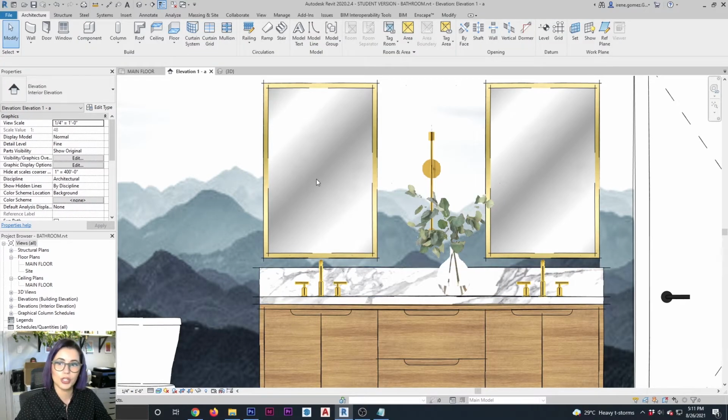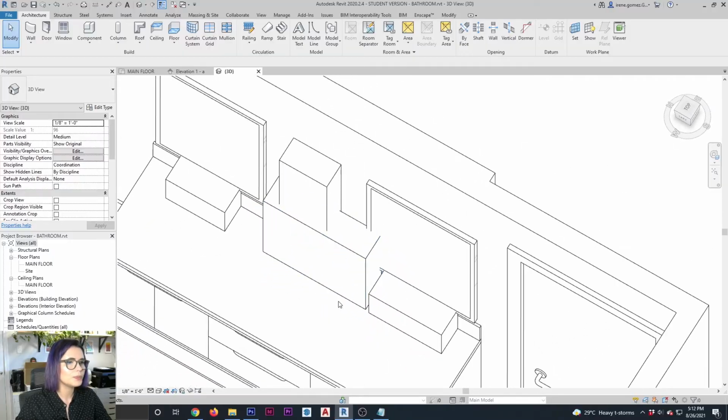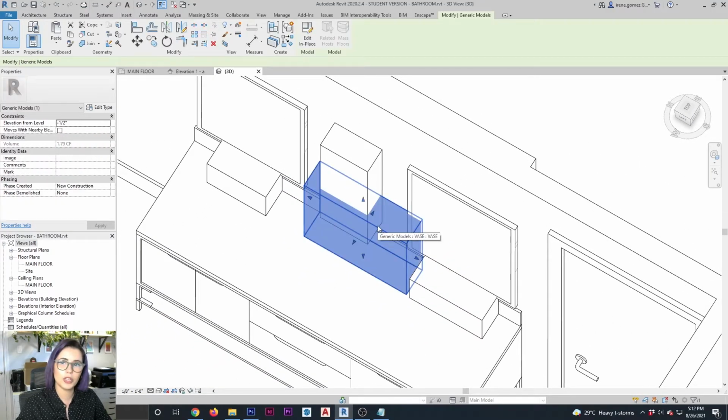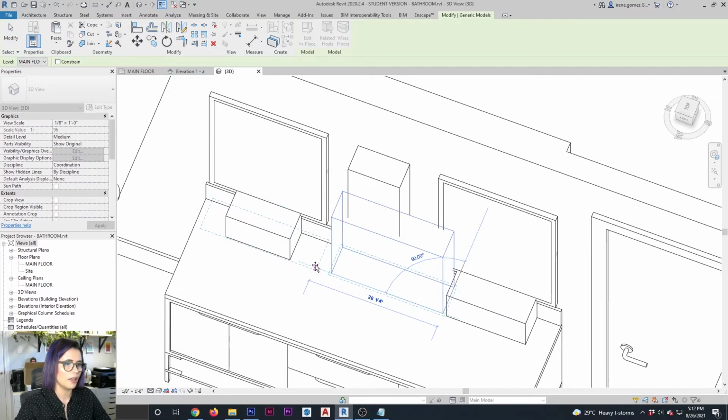And we're gonna finish this exercise with creating those cute Aesop bottles that are like for fancy people. Another thing that you can do is, because your model in place components are all of them instances, so to speak, I don't have to necessarily redo this thing from scratch. I can just go and copy this element. So I can go Control C, Control V, and then just, let's say, position it in exactly the same place or position it anywhere else. It doesn't matter. I'm gonna move it afterwards.